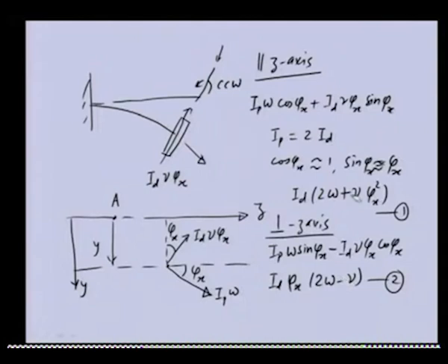So these are the angular momentum components which are acting along the direction of the z axis and perpendicular to it. So now let us see these vectors separately. The first vector, let us say this is the shaft center motion, which is nu. In this particular case we have the angular momentum which was parallel to the axis, which is this one.